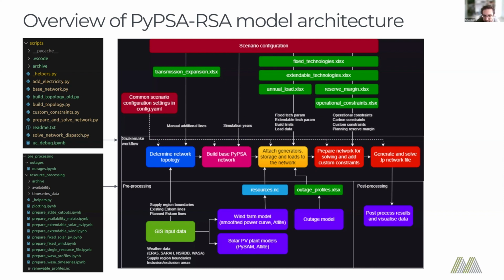In the end, we don't include those reserve constraints in the capacity expansion model because they add quite significantly to the computational time. What we do is still include the traditional planning reserve margin, so that the idea is that it mostly subsumes the operational reserves.